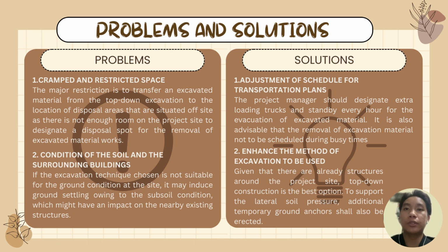Secondly, condition of the soil and the surrounding buildings. If the excavation technique chosen is not suitable for the ground condition at the site, it may induce ground settling owing to the subsoil condition, which might have an impact on the nearby existing structures.